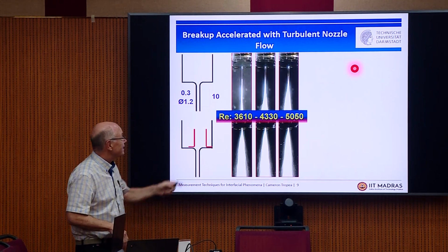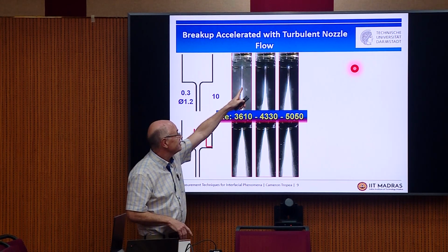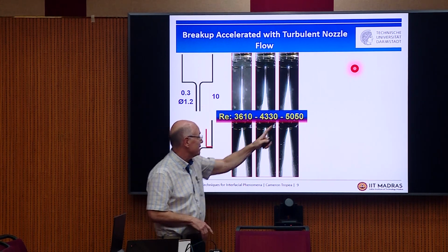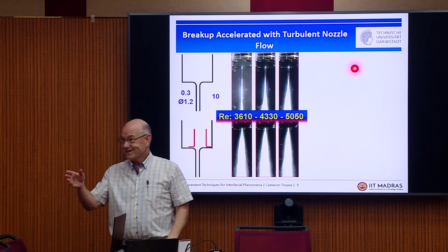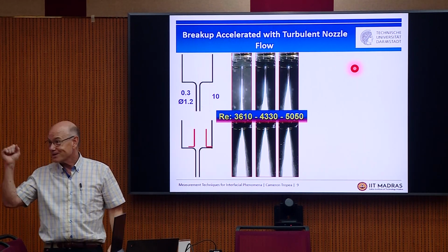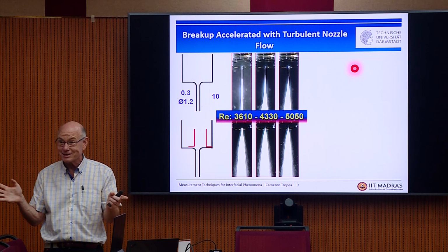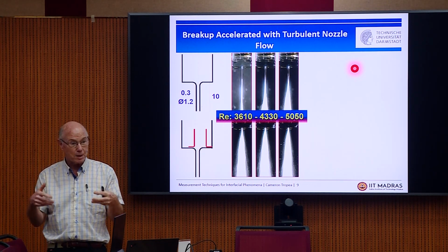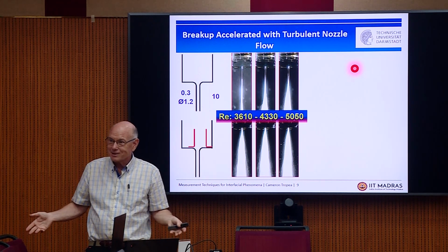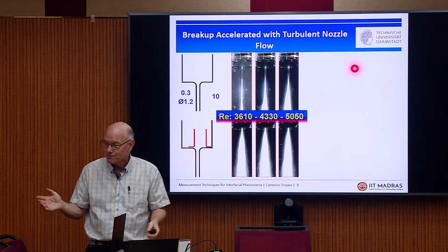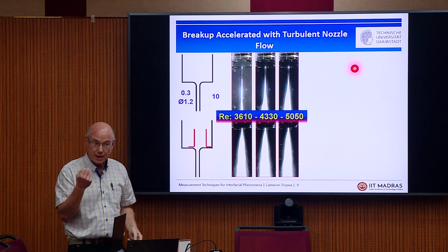You see, this one here doesn't atomize, only at very, very high Reynolds numbers, and this one here atomizes immediately. So if you were an engineer in internal combustion engines and you wanted good atomization for good mixture preparation in your combustion chamber, then you want a disturbance in your nozzle, and then it'll atomize immediately. No? Okay, but this is the idea behind the instability.